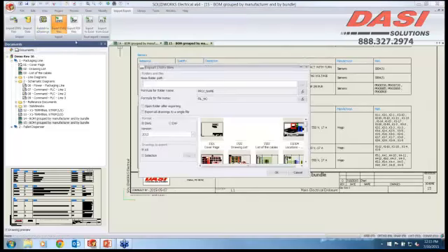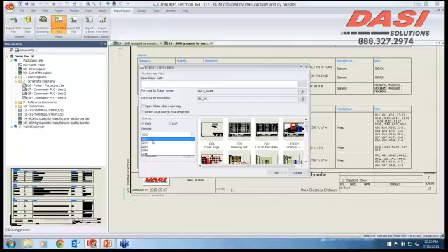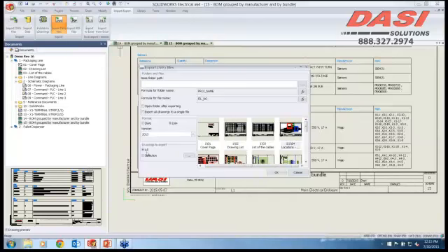You could also export any of our files to DWG or DXF. We go anywhere from the year 2000 version all the way up to 2013, but both in DXF and DWG. So it gives you some flexibility here, as well as being able to select either all of the drawings to export or just part of them.